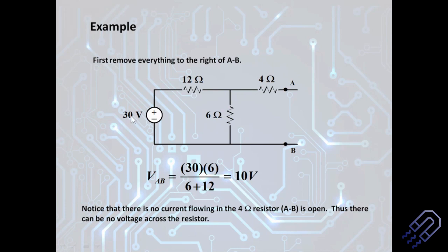Okay. And what is the voltage? 30 volt. Okay. So if we want to find out the current, we can use V is equal to I into R, and then you can easily find out the current. Okay. So once we find out the current, we can find out the voltage across AB. Okay, if we talk about this as A and this is B, and if we say that no current flows across this, along this also it will be the same voltage.